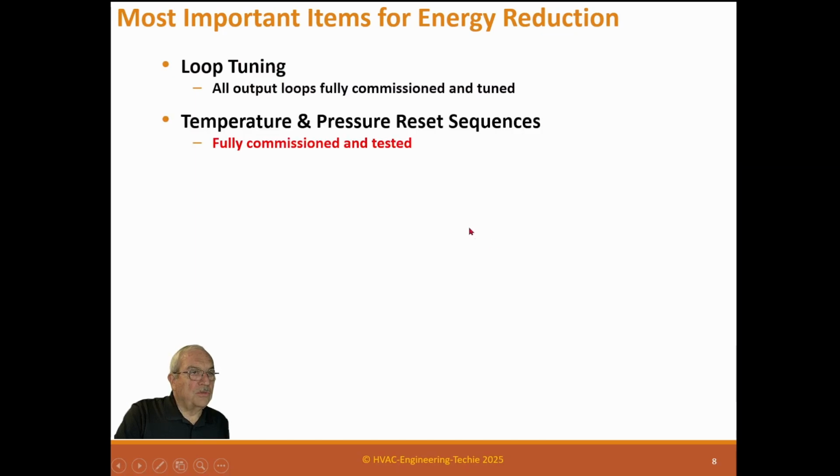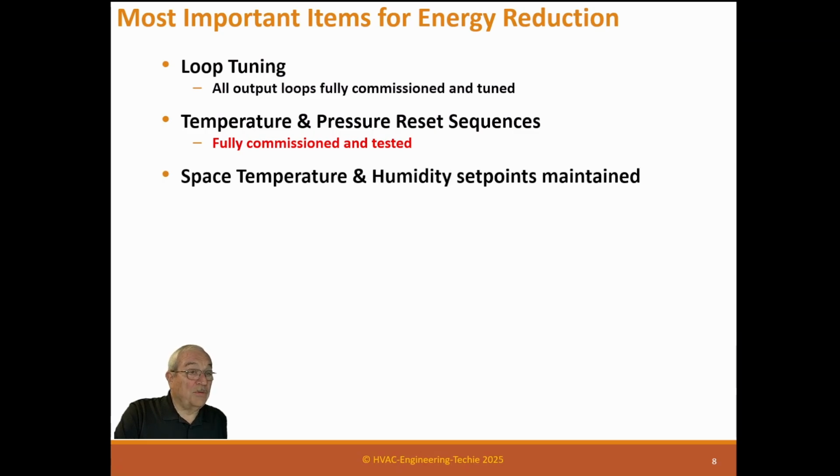Okay, loop tuning is really important. The things that will keep this running correctly for energy persistence, the loops need to be fully tuned. Temperature and pressure reset sequences fully commissioned and tested. Reset sequences provide energy efficiency, but without them, or if they're working incorrectly, they actually provide inefficiency, so we need to be aware of those.